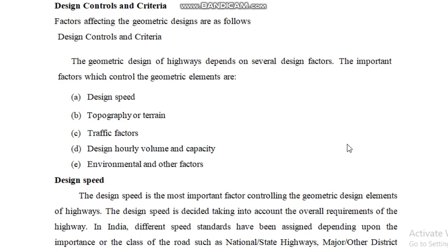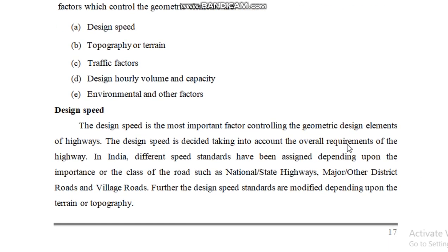Now, how exactly does design speed affect it? As you all know, all highways have different design speeds. It is actually based on the requirements of that project area, and of course, a change in design speed will definitely change the various parameters in the highway geometry. If you want to increase the design speed, then definitely you are supposed to go for flatter curves. You cannot provide sharp curves where there is a need for high design speed.